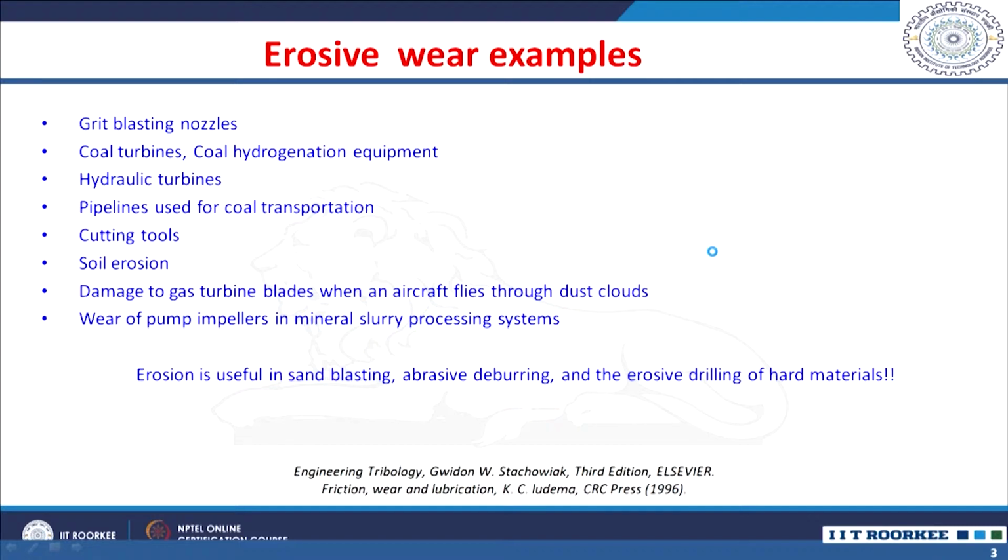Erosion in some cases is useful. For example, in sand blasting you want erosion to happen, but in a controlled way. Similarly in abrasive deburring or erosive drilling of hard materials, you need a controlled erosive wear. So, erosive wear should be understood thoroughly. First, erosion by a liquid.